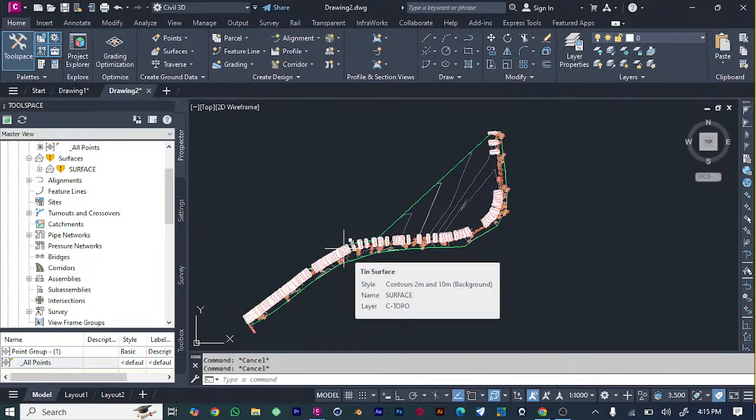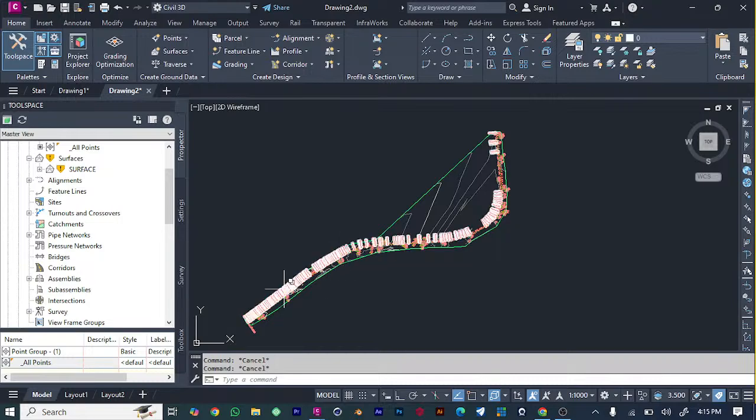I have these things to say to you before we get to create profile. Profiles are like toolbars of your road. It's what underneath that counts. Click on that profile tab, create profile, surface profile. It is that part where you finally realize your terrain is smooth sailing or full of surprise mountains.